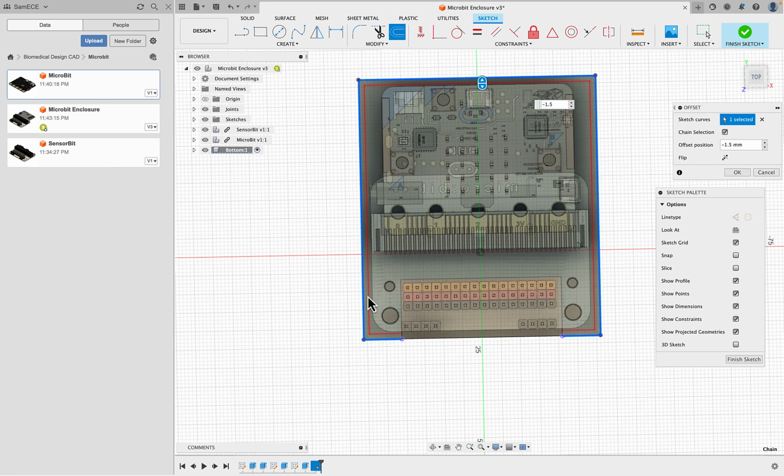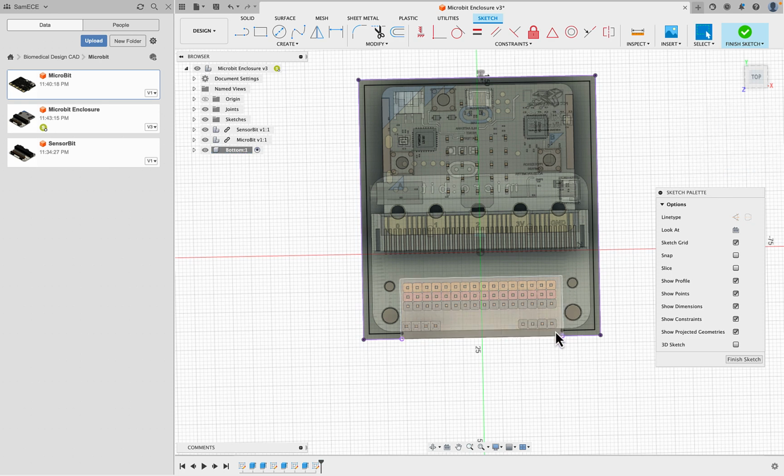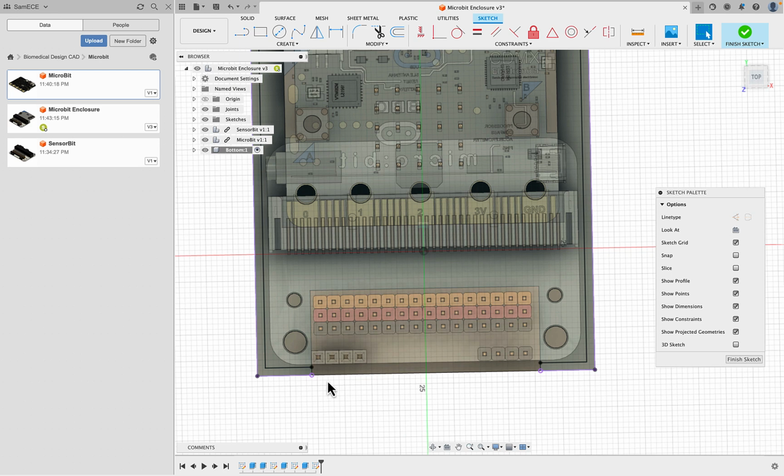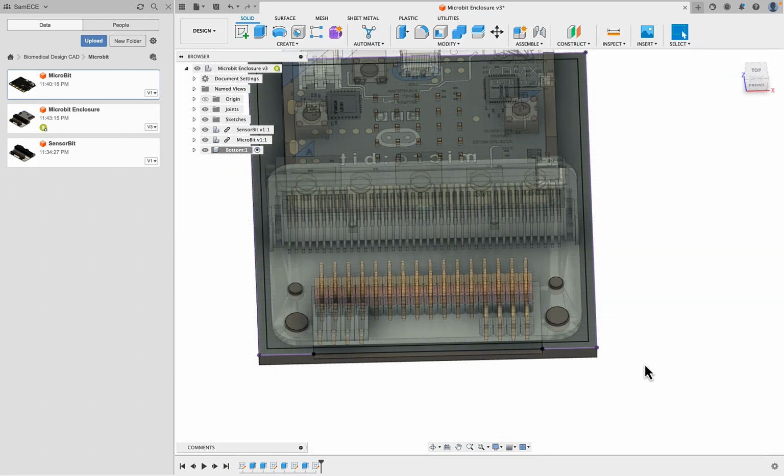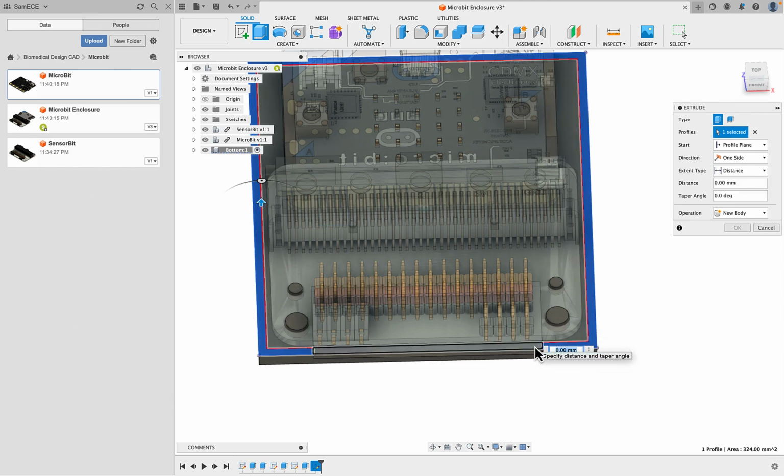So again, just looking through, seeing whether or not my interior wall touch my design. Doesn't seem to. So we just need to close these 2 in the bottom. So hit L and close the outer one, and L and close the inner one. So now I should have this area and this area to extrude. So hit finish and choose E, select this and this.